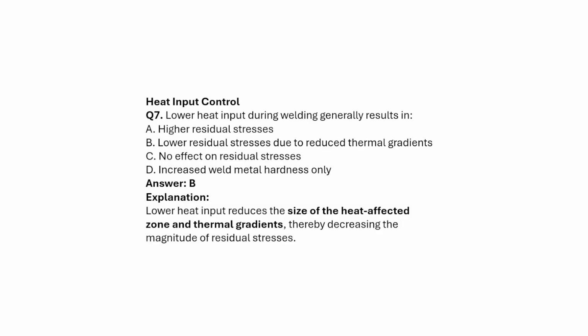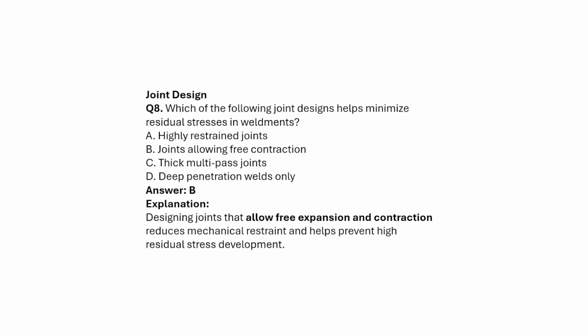One way is that if the heat input is high, we have to provide preheat treatment so that the thermal gradient will be low. Or if you provide less heat input, then also the thermal gradient will be less, so that will reduce the residual stresses. Lowering the heat input reduces the size of the heat affected zone and the thermal gradients, thereby decreasing the magnitude of residual stresses. Which of the following joint designs helps to minimize the residual stresses in the weldments?